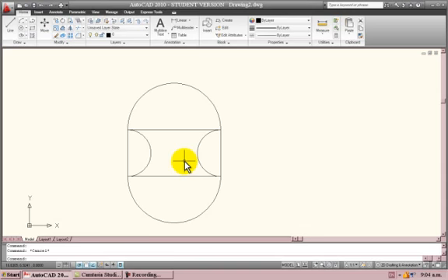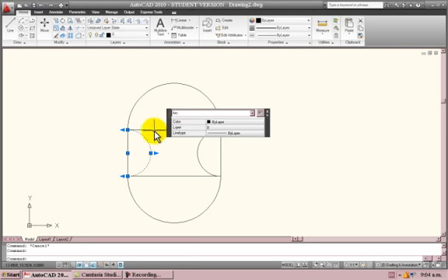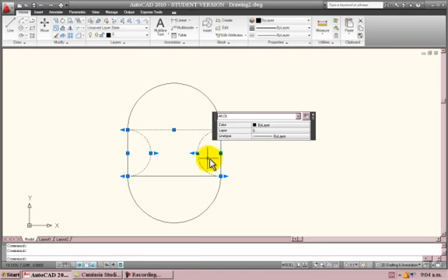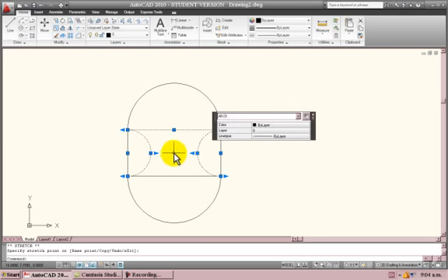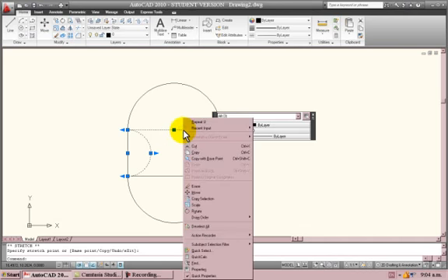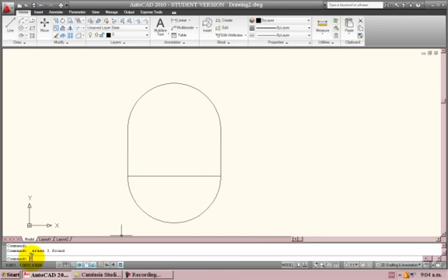Another method is by leaving the command line blank. So select 3 objects, click, one there and one there. Now what you can see immediately are these drag bars, so we can just move that in and out, or we can just change the dimensions of the particular part of the drawing we've clicked on. But remember, we're focusing on erase, so we simply right click and we can erase just like that. Just as easy. Remember, down the command line, press U, and they're back again.